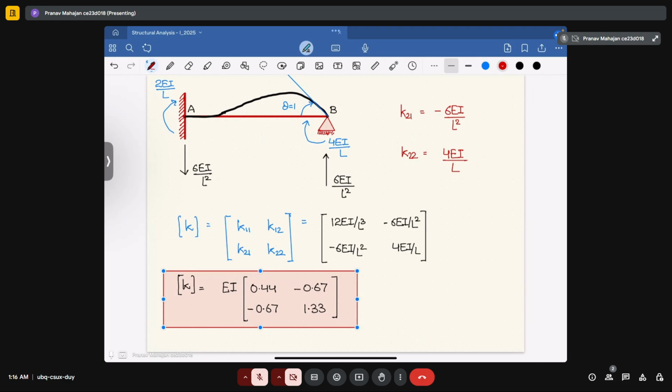After that, we moved to moving loads, or you can say influence line diagrams, where we have seen how the proportionality of load should be provided to obtain maximum bending moment and maximum shear at different points of the span. We have used the Muller-Breslau principle in that. After that, we introduced the force and the stiffness matrix methods.